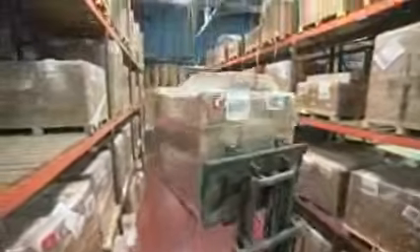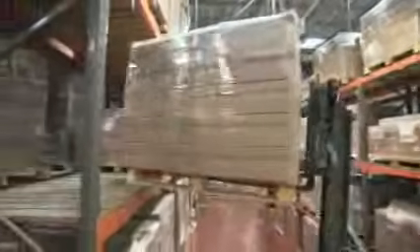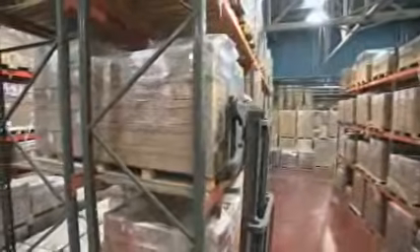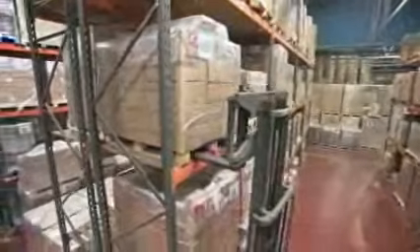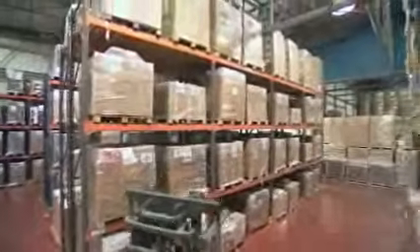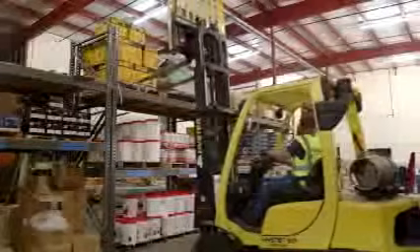When stacking or tiering, tilt backward only enough to stabilize the load. Use extreme caution when tilting loads. Do not tilt forward with the forks elevated except when picking up or depositing a load. Prior to raising the load, make sure there is adequate overhead clearance.